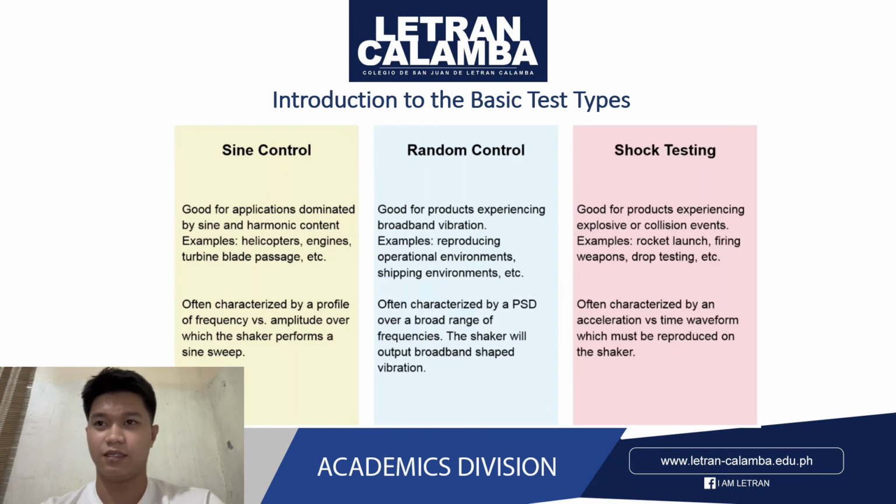Shock testing is good for products experiencing explosive or collision events. Examples are rocket launch, firing weapons, drop testing, etc. Often characterized by an acceleration versus time waveform which must be produced on the shaker.